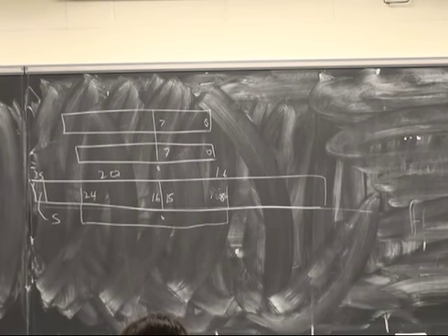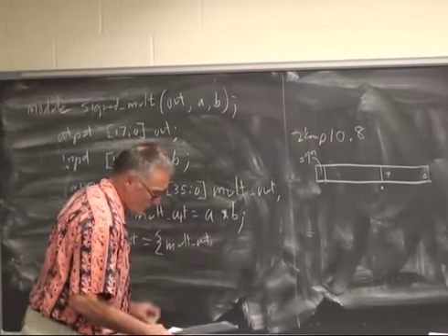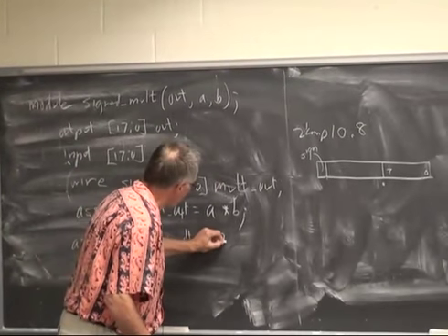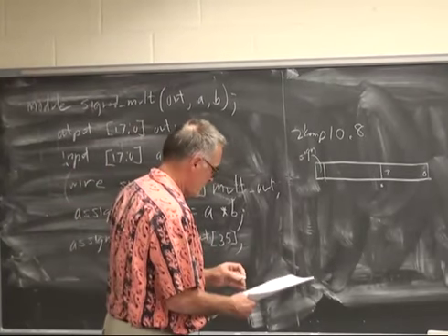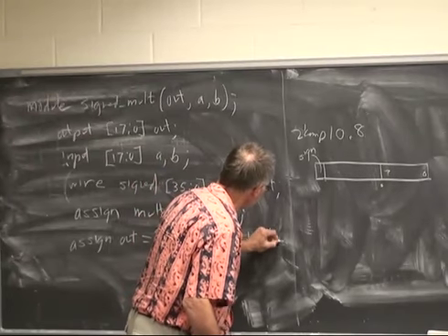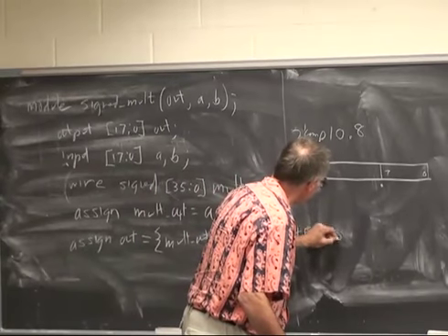And so, yes, it can overflow. And you can't allow that to happen. So here we're going to assign the output value as the concatenation of mult out bit 35 concatenated with mult out bits 24 down to 8.